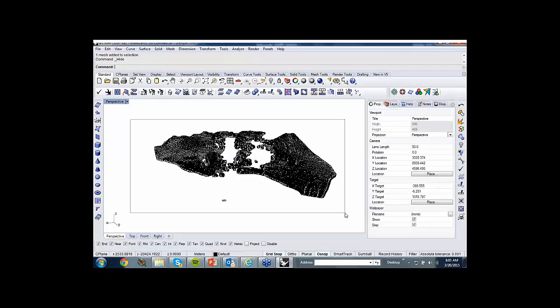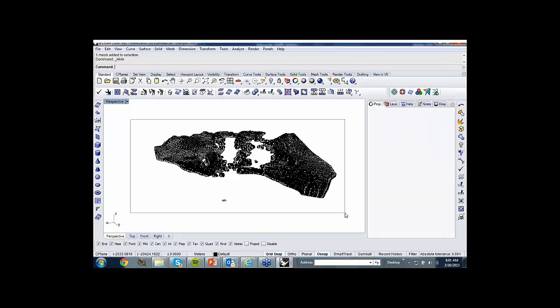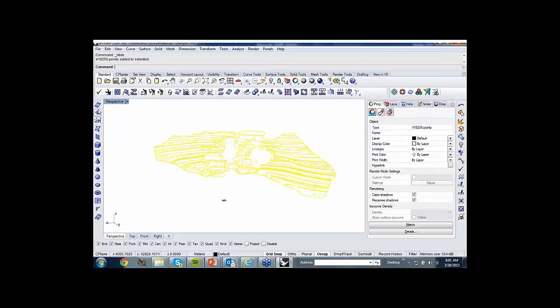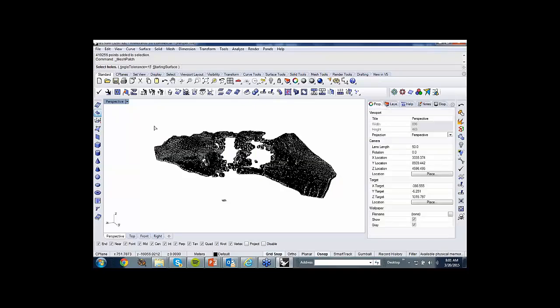Now I'm going to tell it to mesh patch, just as we used mesh patch before. It asks me for some angle tolerances and things like that, but it's very quick normally at creating a triangular mesh essentially obtained through an operation called Delaunay triangulation. So it will create a triangulated object from this cloud of points.